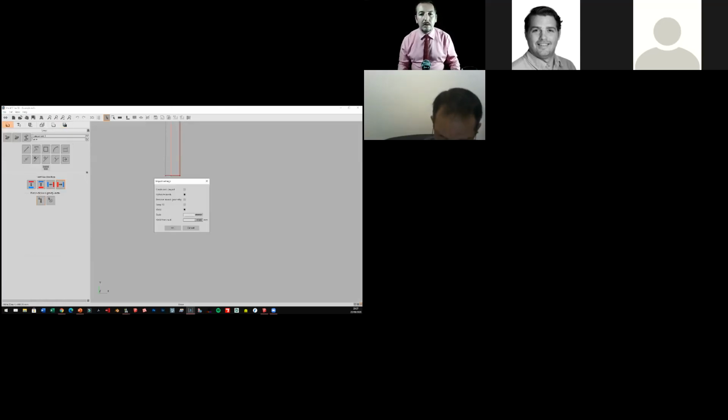Now, see here, you have a scale, a weld threshold, which honestly I don't play with, I'm afraid, because it just doesn't work out. If there's something wrong with your model, go back and nearly start it again, because that will actually be quicker. Or identify where the flipped face is or something like that. Most of the time it just fixes the geometry and that's fine. Optimize, yeah, leave everything alone.